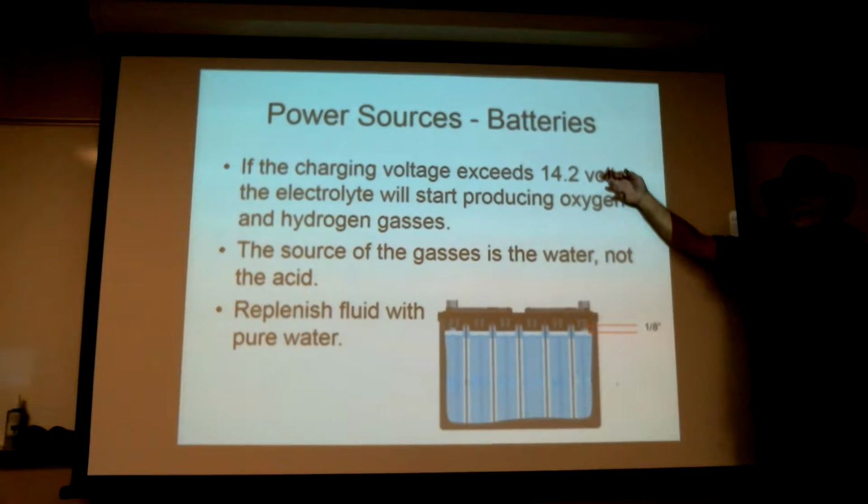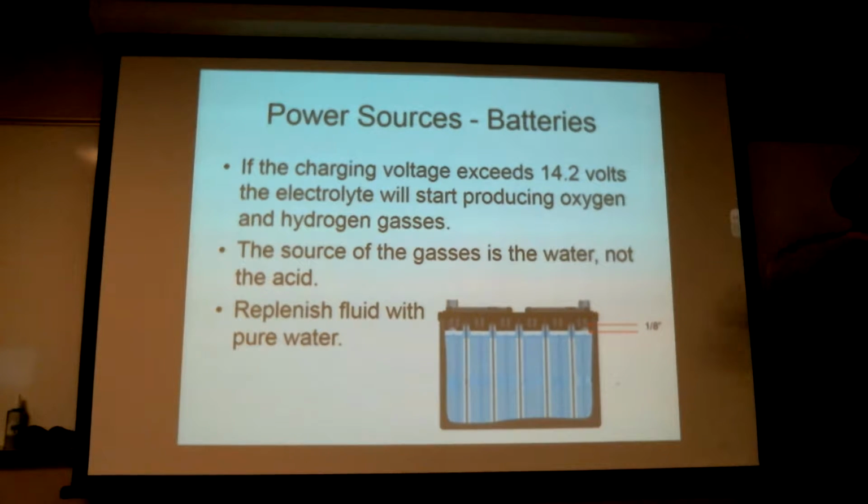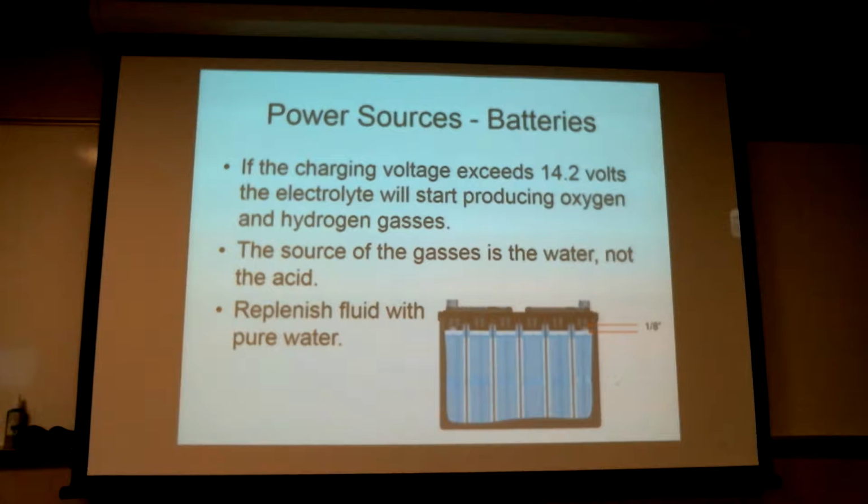Yes. That's what the battery charger or the power supply does. It'll bring the voltage up to bring the current up. So in truth, you're going to be doing some current limiting there. Now, that said, it's really not directly a function of the voltage, it's a function of current. So I could also have a voltage limiting device like a voltage regulator and still hit the battery with 60 amps, which is exactly what your engine does.